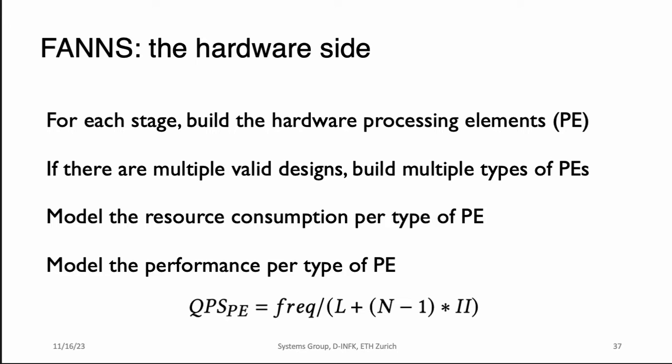For performance modeling, because we already know the architecture of each PE, we know the pipeline depth of it, and we know what is the pipeline initiation interval, and then given a frequency expectation, we can now model what is the time a PE takes to process, let's say, n input elements.